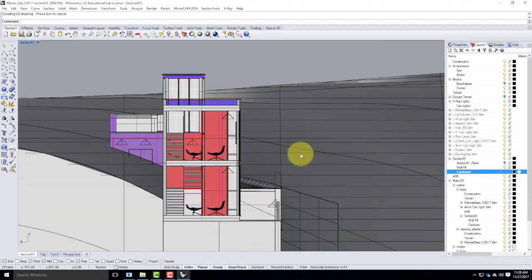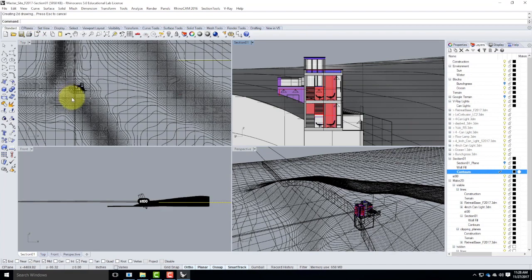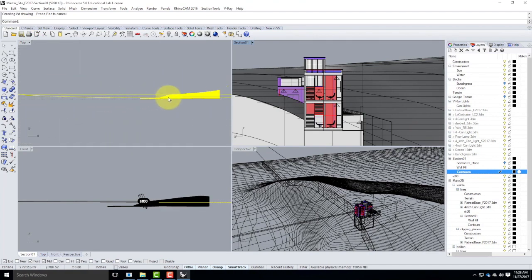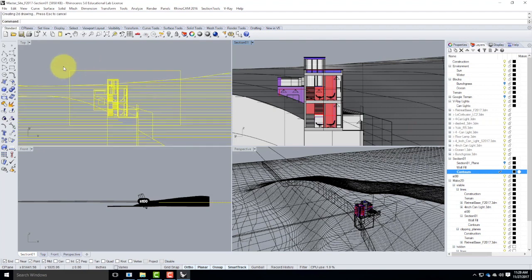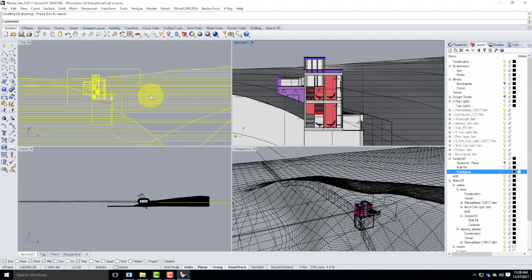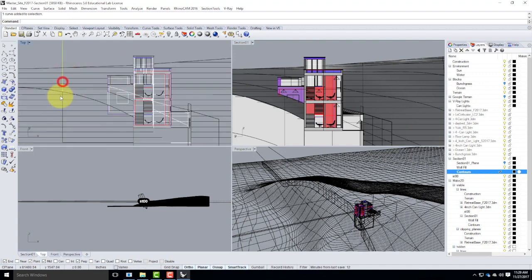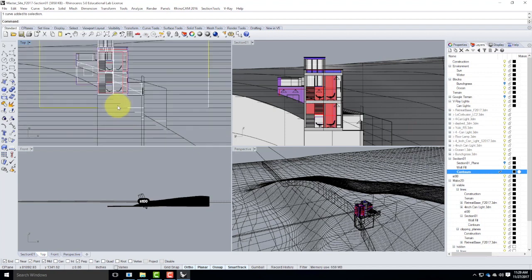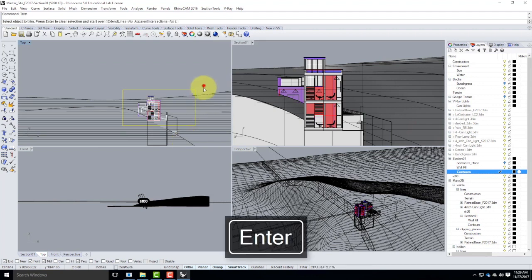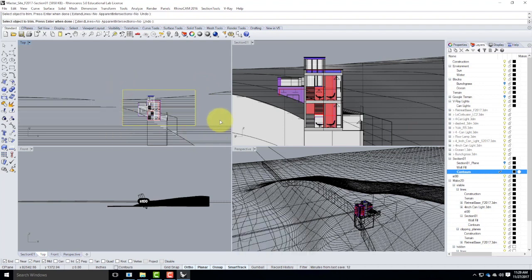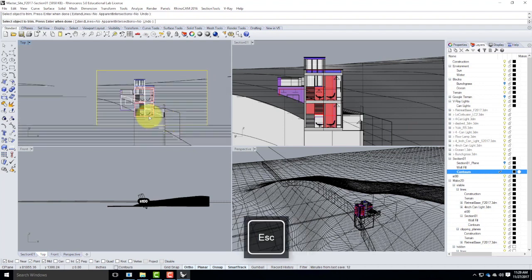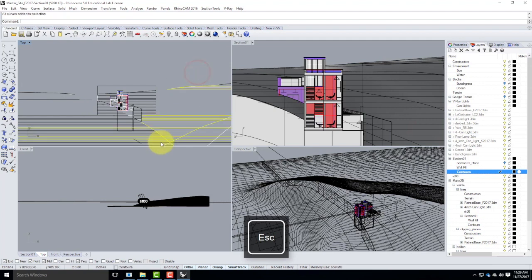Okay, so it finished the Make 2D. I'm going to go ahead and double-click on my section, get back into my top view, and I'm going to see the Make 2D sitting over here. So remember, the only part that matters is the part that's inside the square. So I'll use that rectangle here as a trim. There we go. I'll type trim. We'll get rid of the stuff that's outside. And then I can go ahead and delete all this extra stuff because it doesn't matter.